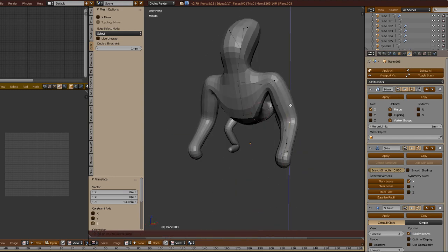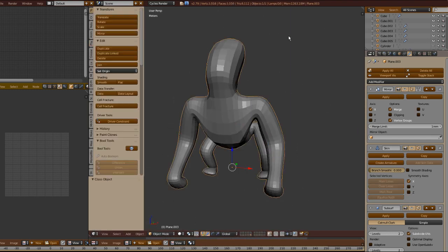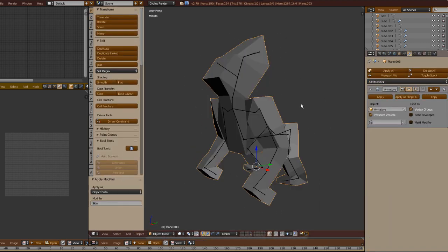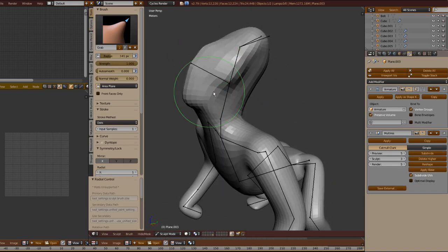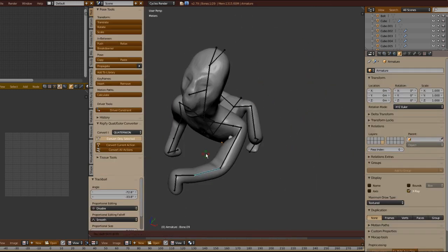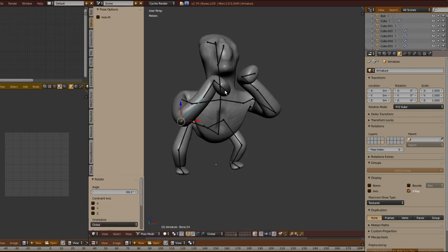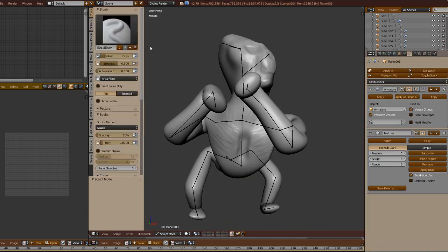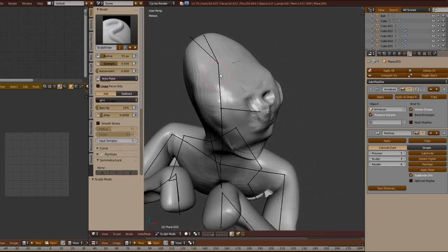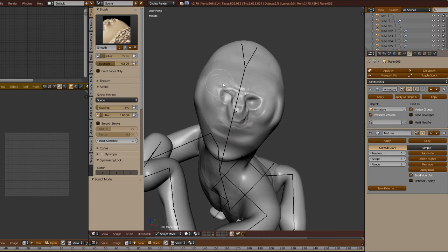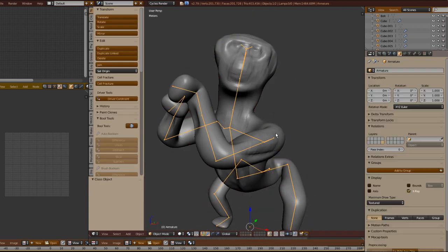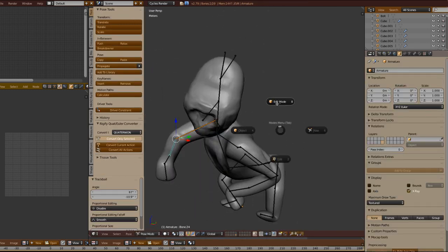There is a very powerful feature. After the user finishes creating the mesh, the user has the option of creating an armature. This means that the user can pose the mesh through an automated system of bones and weight influence in the mesh. It's a basic rig system created with FK and IK systems. This is wonderful. I know, people may think I'm exaggerating about rig and skinning, but this kind of single mesh system and a unified system could provide any kind of implementation.